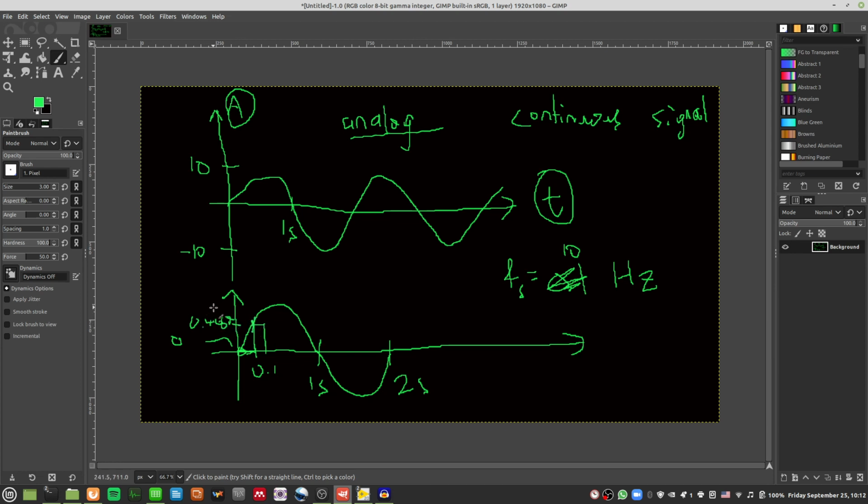But sometimes your digital signal will force it to somewhere between 0.4 and 0.5. So your amplitude will not be recorded as 0.4467. The sampler will read that 0.4467 is closer to 0.4, so let me record this value as 0.4, for example.